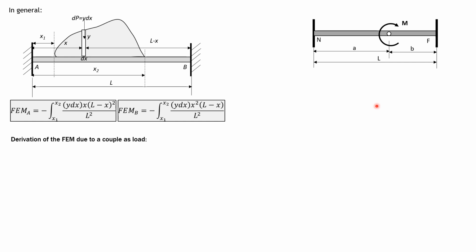So we have no other means of deriving it except to apply the basic approach, which is considering the moment diagram by parts. So let's make the far end as the wall. In these formulas that we're going to derive, let's assume that all fixed moments are clockwise. If the result is negative, then it means the fixed moment is counterclockwise.